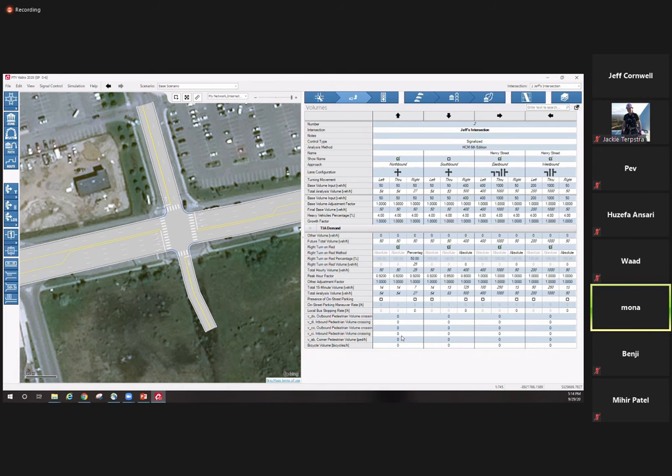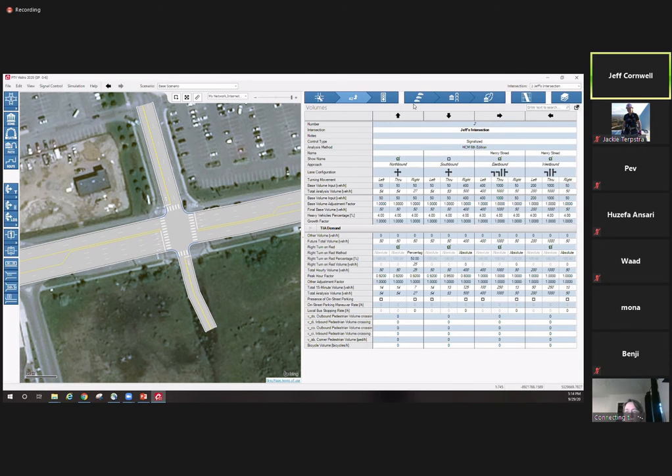No, I have pedestrian volume. That's it. One thing, 0, 0. On top of that, total analysis volume. Are you in HCM 6th edition? Yes, I am. And you're on Signalize, I think. And I'm on, yeah, volumes, second tab after intersection.